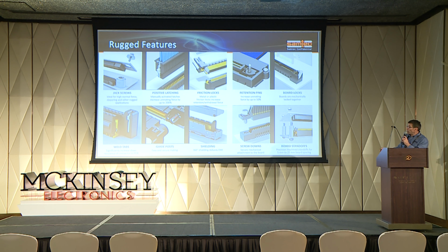Many of our products have got guideposts for better alignments, and again, weld tabs. So usually a -WT at the end, we'll put a weld tab in. That'll give better security on the board. So a lot of our series are including many of these retention features. In some cases, for edge card sockets, we've got board locks. So if you're doing edge card to edge card with a riser card in between, separate your boards, the board lock will hold it into one side and keep things secure for you.